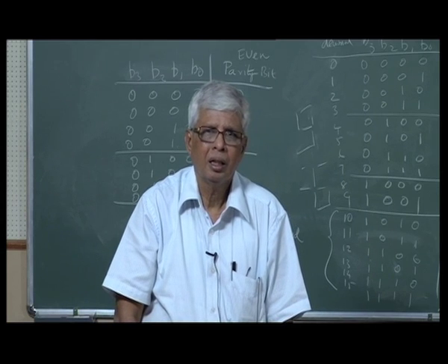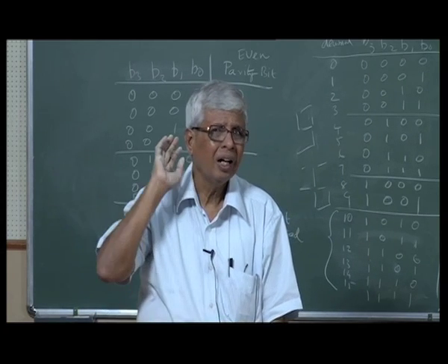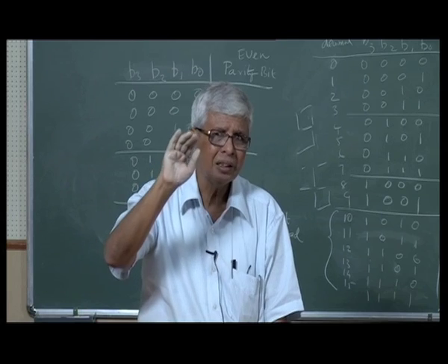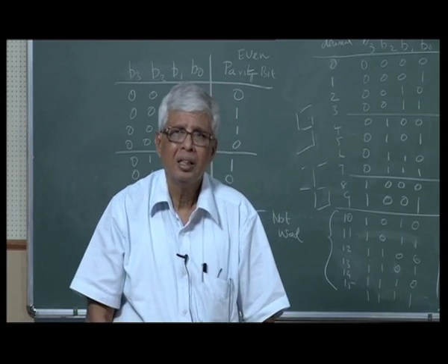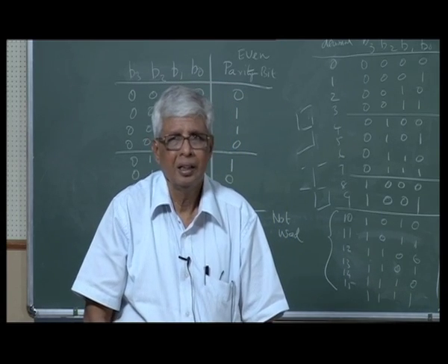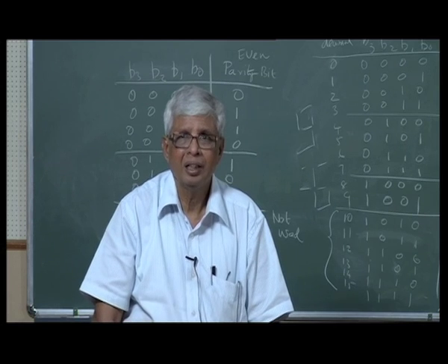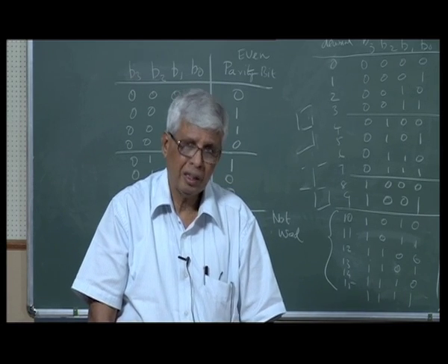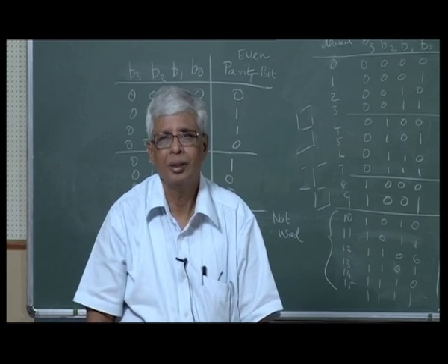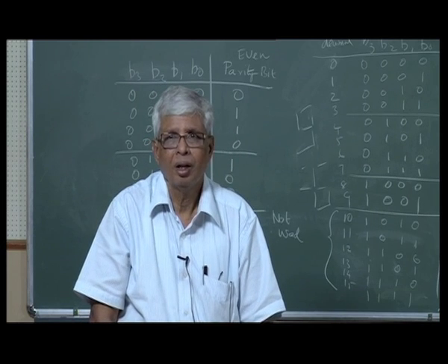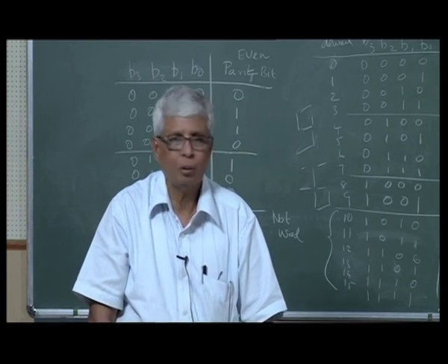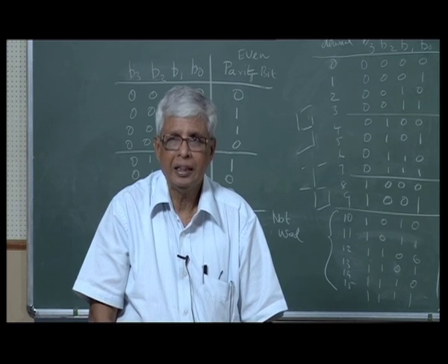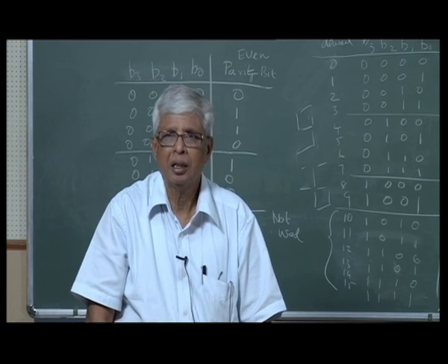Sir, in 3-state case, high impedance state you said. Say it again slowly. In 3-state case, high impedance state you said. High impedance state, yes. In that state, output will not come. Output will not be there. There will be no 0, there will be no 1. It is as if it is an open circuit.